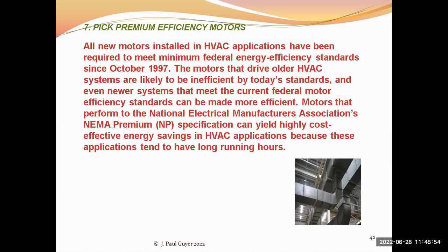The premium efficiency motors, this is a good opportunity to look at, because these are a relatively new piece of equipment that's on the market, and it may be significantly cost effective for you to replace the fan motor in the air handler with premium efficiency motors and be able to have a smaller motor that will still turn the fan so as to deliver the required quantity of air to the occupied spaces.